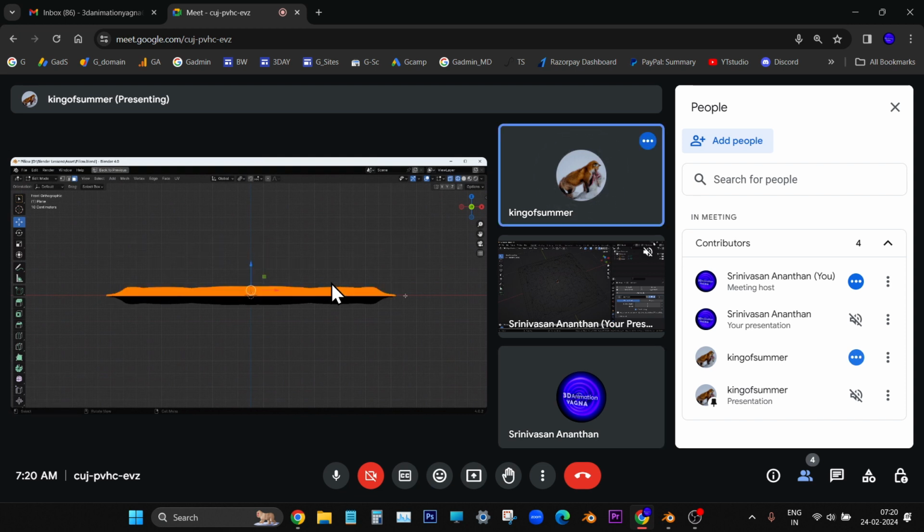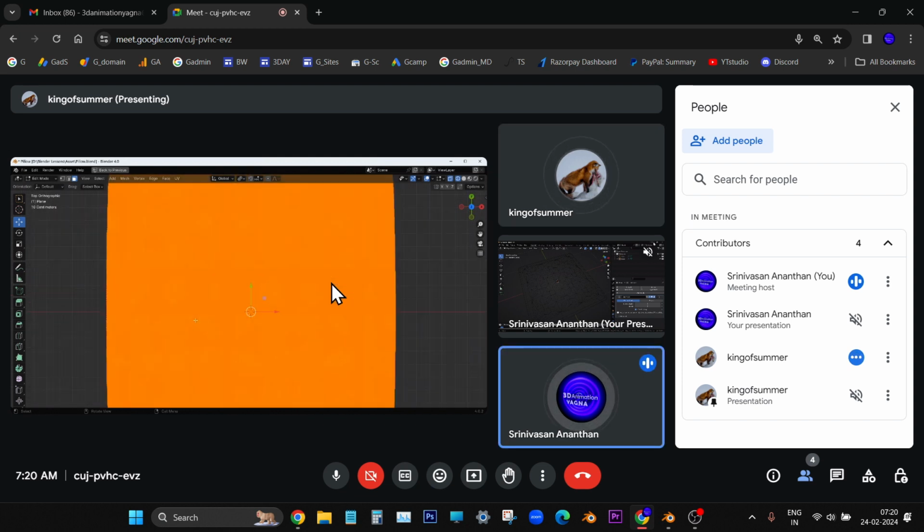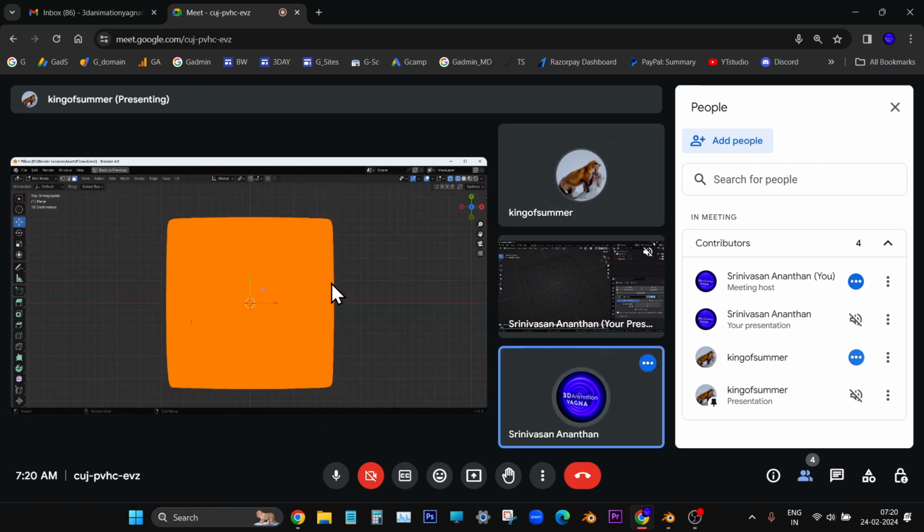Yeah. Yes. Correct. Exactly. Very good. Now let the selection be. Don't deselect. Press 7 on the keyboard, so that we can check in the top view also. Yeah, it is all selected. Nice. So with this simple way of selection, we can do the UV unwrapping for a remeshed object, because we cannot easily mark seams for this remeshed object. I will show you.